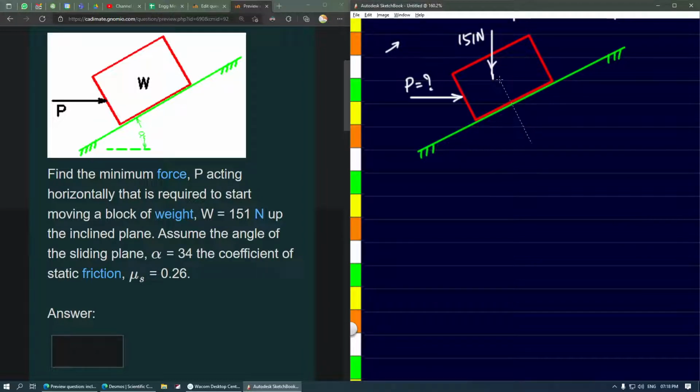So we'll have another normal reaction here in this direction, and because the motion is impending towards upward direction, friction will try to avoid that motion. This is the direction of friction. So normal reaction, let us call it as N. Then the friction force will be mu times N, and these are all the forces that are acting here on our object. We will have to assume the direction for X and Y directions.